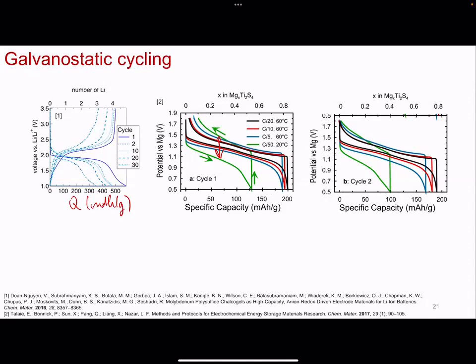And so sometimes I'm wondering, what's the best way? Can we just forget the first cycle sometimes and just calculate that lithium after the first cycle to represent those? I guess, is it best to forget about the first cycle and then just plot and say this is cycles 2 and on, or even 3 and on, right? Because some commercial cells are pre-cycled for a few cycles anyway, right? And I suppose, yes, if you communicate that entire caveat.